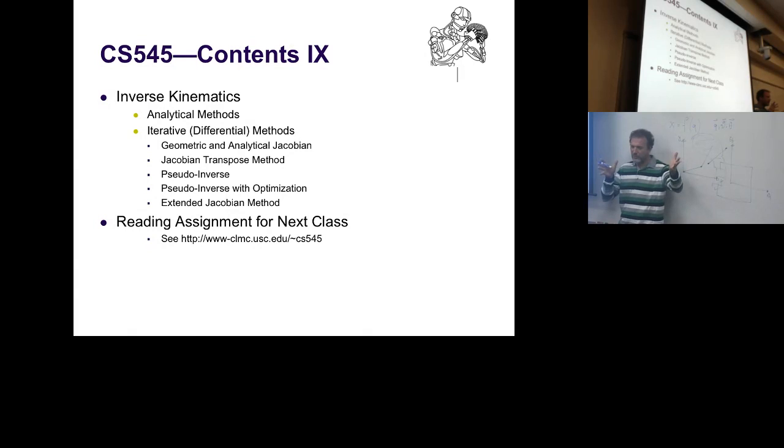If you can formulate the world such that essentially everything is quadratic bowls with constraints, simple constraints, which are inequality constraints or equality constraints, and you've got to make sure that certain conditions are fulfilled, then you can very, very rapidly optimize and find an optimum, a minimum solution. And the important story today is that whatever we're doing when it comes to inverse kinematics actually has an interpretation in terms of optimization. And that is where this connection is made.